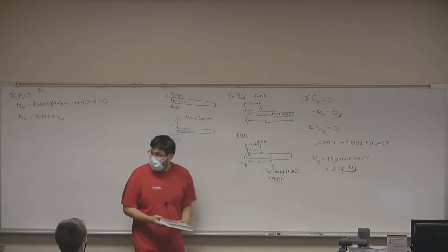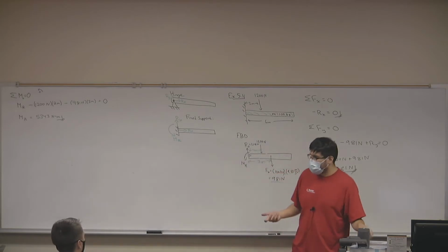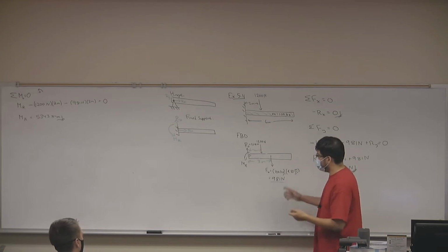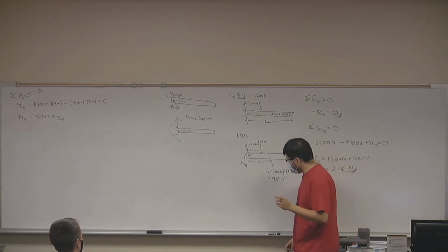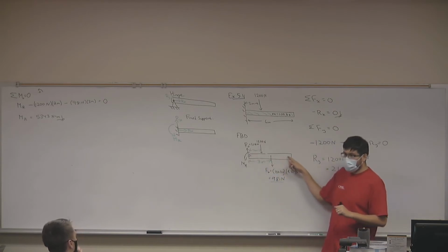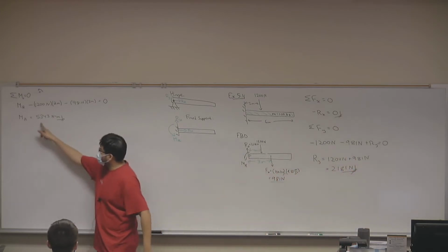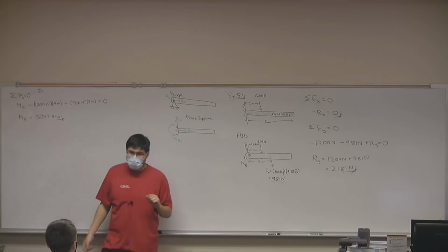So that's why we have to include it. Okay? So it is a force. It's just a different type of force. It's a rotating force, not a linear force like what we're used to. Okay? And here you bring an interesting point. It doesn't matter where in the beam this moment is applied. We still have to include it in our equation. It doesn't matter where it is. We'll still include it. It will still be MR.